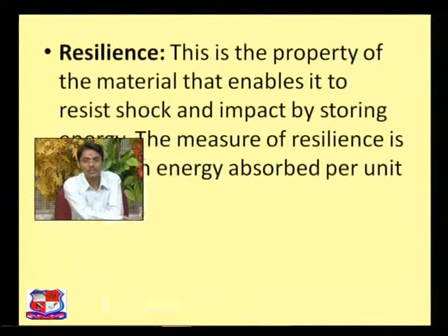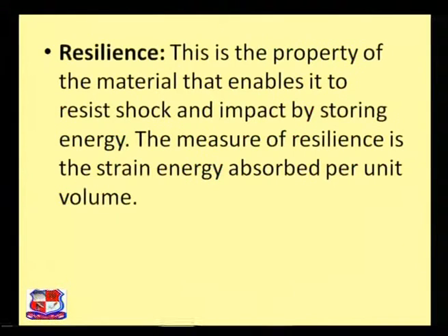Now dear students, we will understand resilience. This is the property of the material that enables it to resist shock and impact by storing energy. The measure of resilience is the strain energy absorbed per unit volume. In other words, we can say that whenever a material or an object can resist shock and absorb energy, or we can say it can store energy, we can say the particular material has a good resilience power.